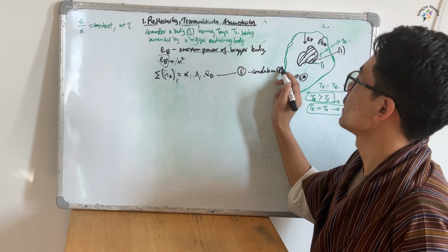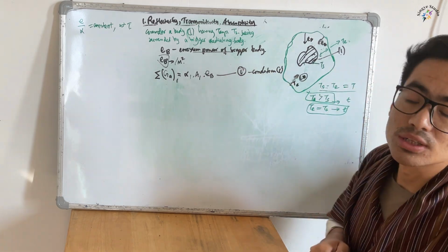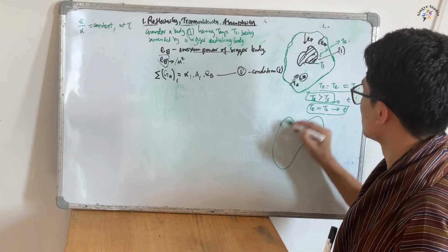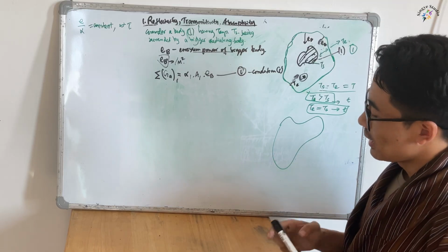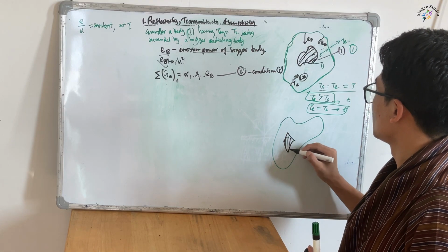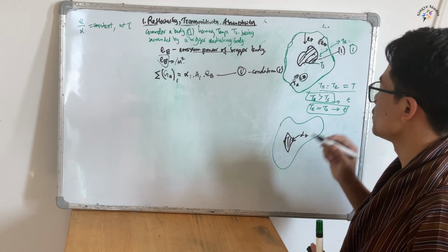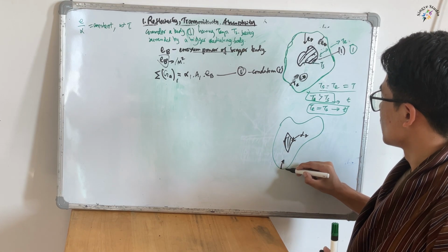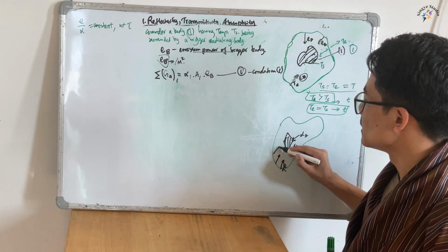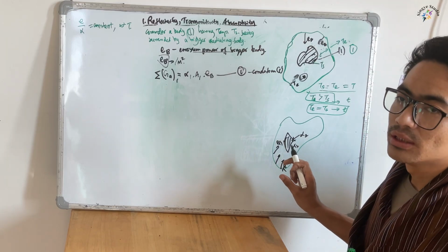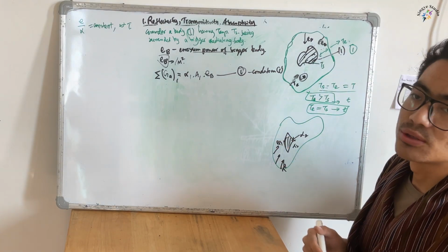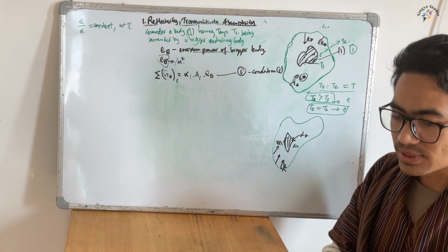Now I want to change this body into a different body, so that my same boundary is here like this. You can say this is condition 1, and then my body is different now. It's a different shape, and it has an absorptivity of alpha 2, and the same thing happens with Te and Ts. So this EB is all over the body, but how much is absorbed will depend on alpha 2, similar to the previous case.